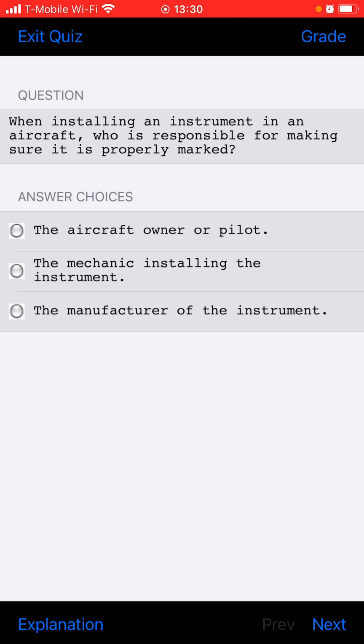Describe the safety precautions that should be observed when servicing an oxygen system. Avoid all contact with petroleum-based oil or grease. Don't smoke. Keep everything very clean. Service the system outdoors if at all possible, and keep the caps on the bottles to protect the valves.